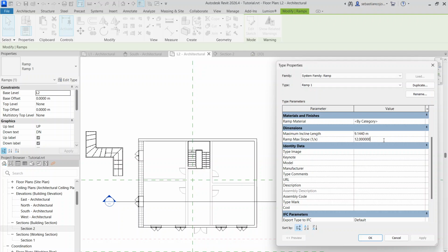8 multiplied by 10 is 80, 2 multiplied by 10 is 16, so it would be something around 96. If it would be 9, it would be 90 plus 18, so it would be 108, somewhere in between 8 and 9, something like that. That would be 8 or 9%, but you can make it steeper to around 15%, and you can adjust and calculate accordingly and set the slope here. Let's say I want it steeper, I want to be too exaggerated and have 20%. I can divide by 5 or by 6. Let's say I divide it by 7, and that should be more okay.